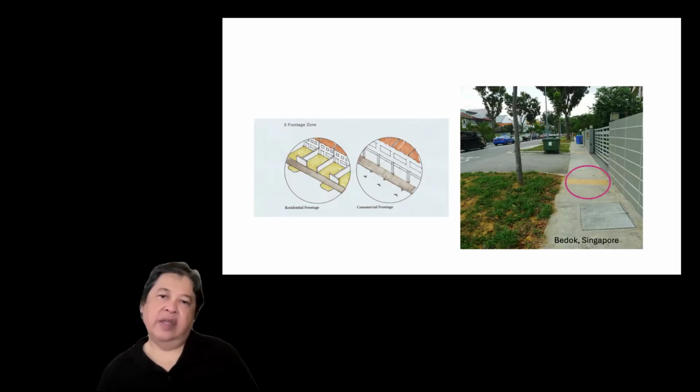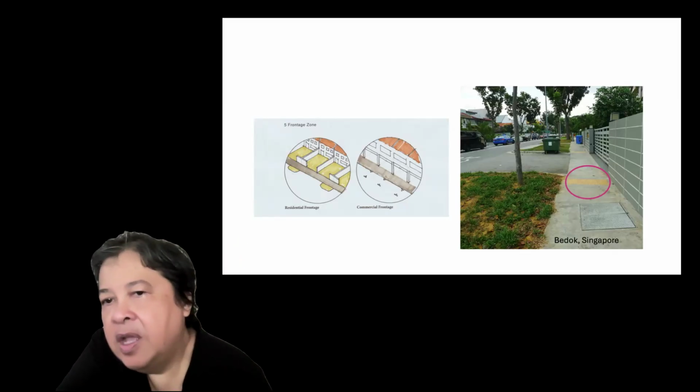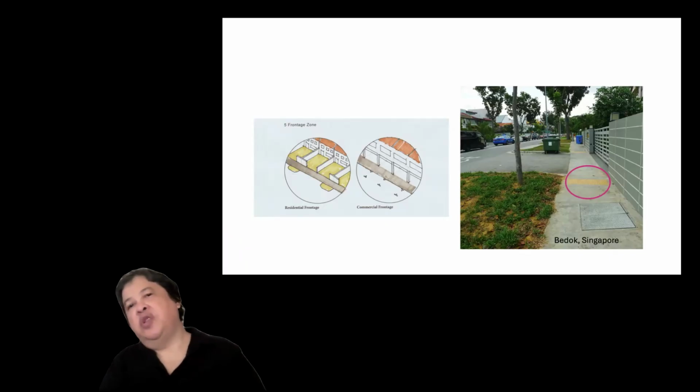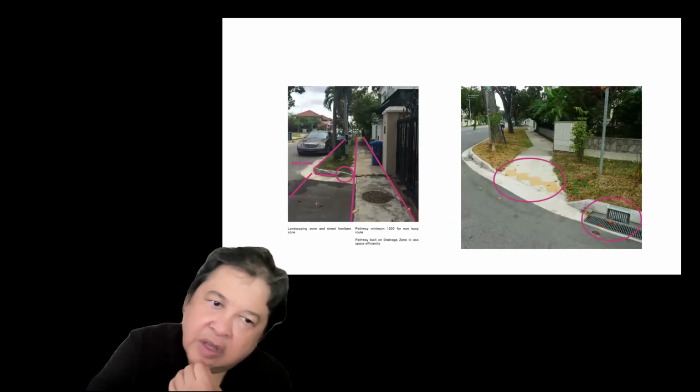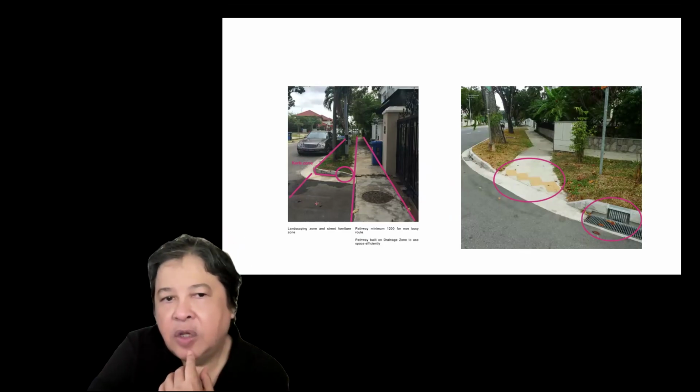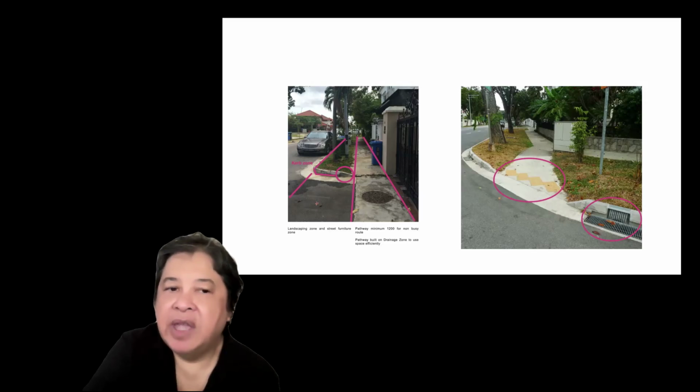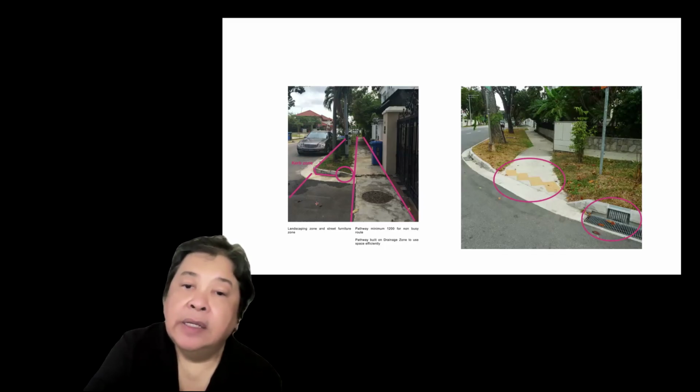And that is a protected pathway that allows people to move about in a safe manner. All the manholes and anything to do with street furniture is taken away from that pathway. The design of the curb could be higher, like you see with the landscape area, but the one inside does not necessarily have to go high.